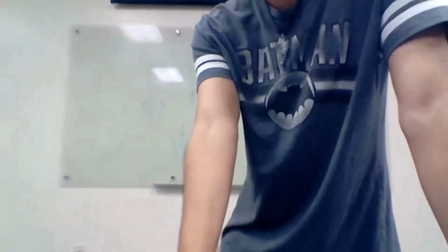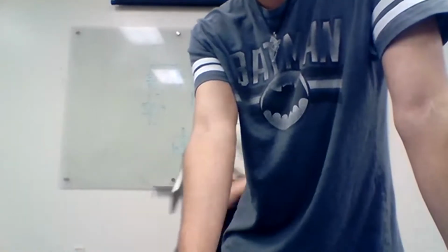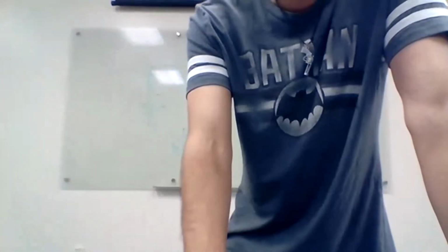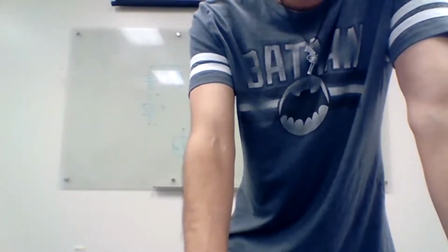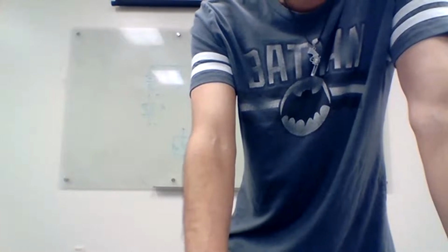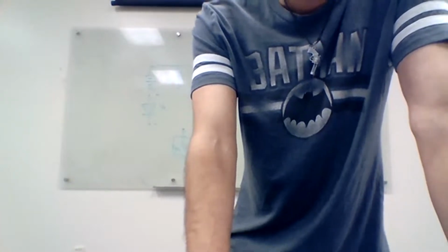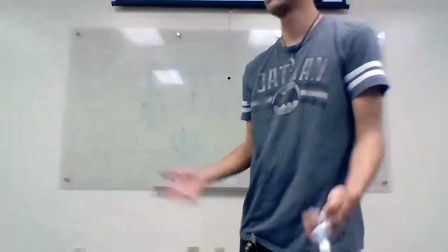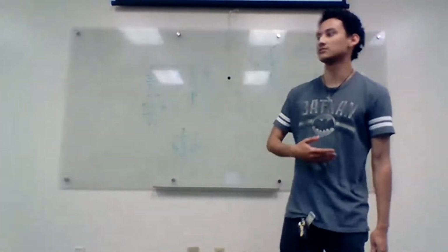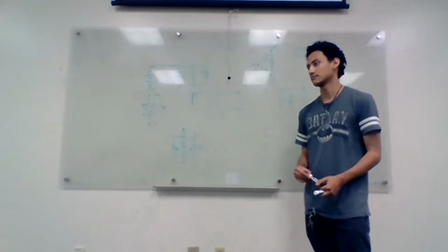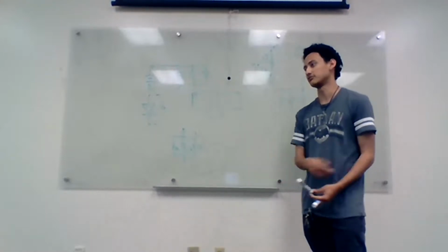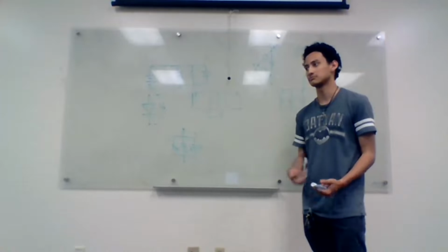If you want to take the derivative of that, you're free to. But the derivative of that is what gives you your C sub D, and it turns out to be an exponential. That's why it's only in forward bias, because an exponential in reverse bias would be 0.